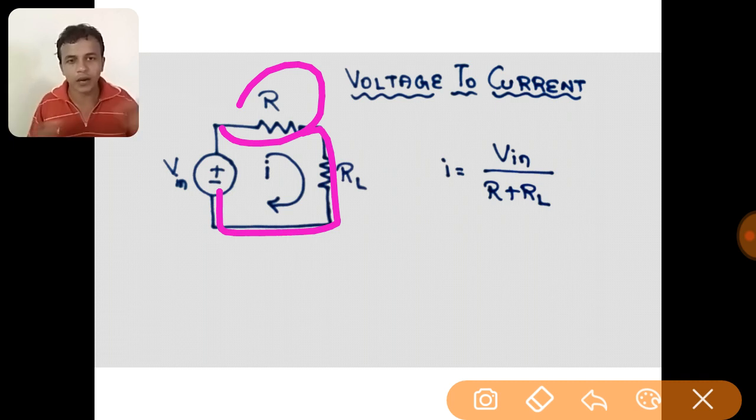The signals measured using sensors have to be transmitted to that point. The sensors convert any physical parameter into an electrical signal, in the form of voltage. When this voltage is transferred to the measuring point, it may get lost while transmitting through the cable. Whereas if it is converted into current and transmitted through the cable, there won't be any loss. The reason is, in parallel connection voltage is constant, and in series connection current is constant.